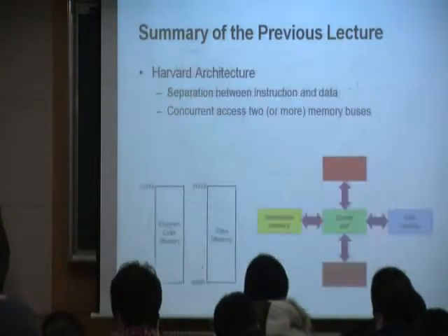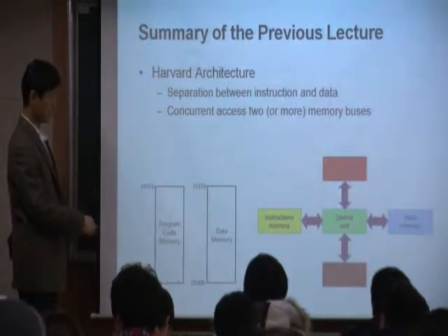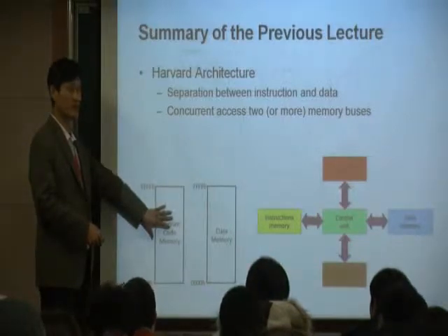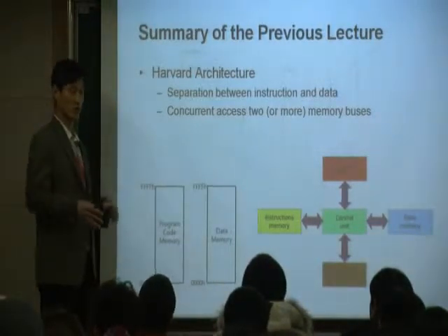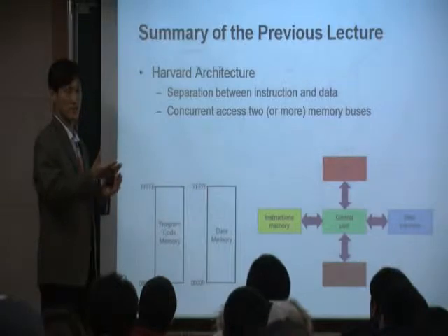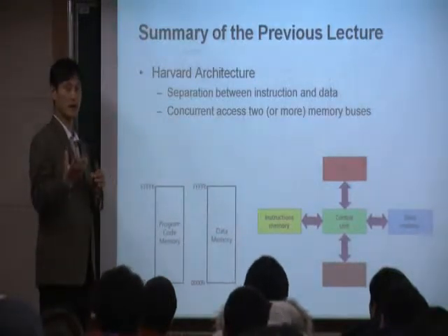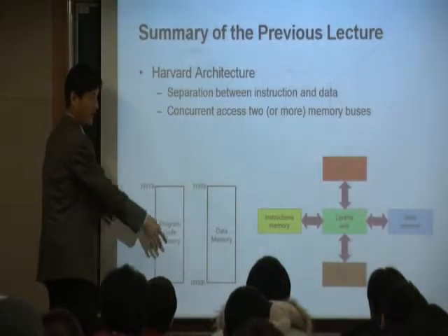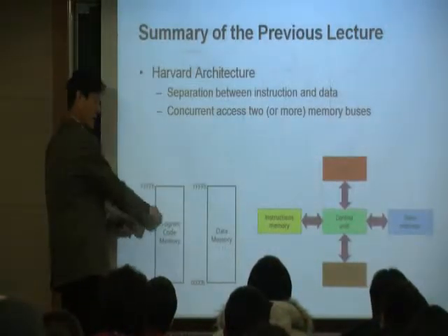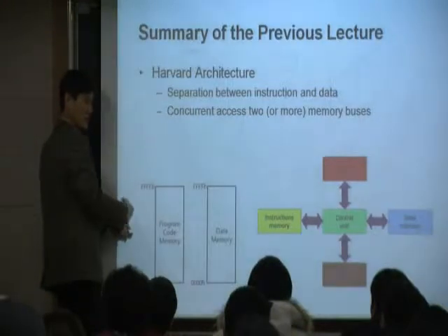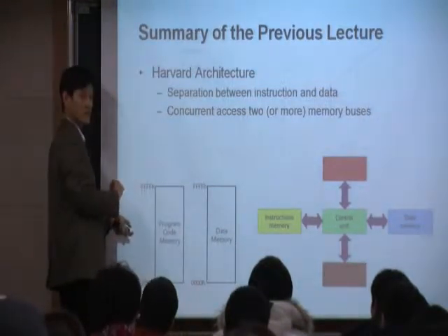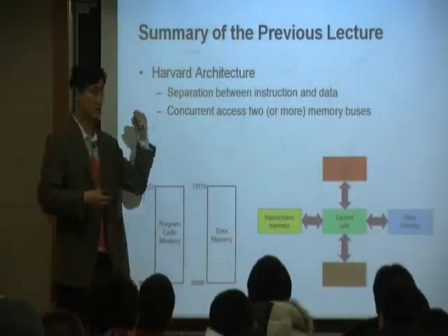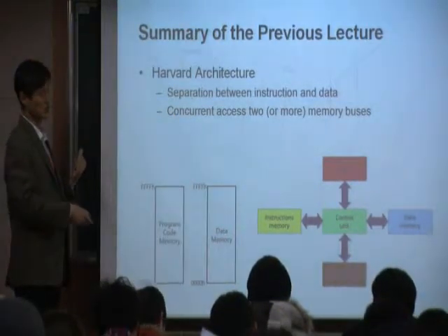Fetch basically means that, let's say you have some program here, okay? Your program is downloaded into here in a binary format, right? Your original code is like a C function, C code. You compile it, make a binary, and download that binary here into some other location, right? And the CPU will go there and read it one by one. And reading it means a fetch. What is a fetch? In English, fetch means go there and get it. That's fetch, right? So fetch is the first step to do.